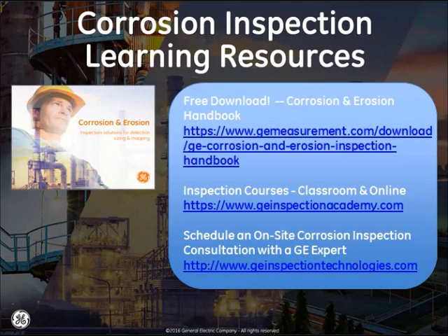If you do have a very wide area, for example, an area that could be 2 feet by 2 feet, and somewhere within that area you think you have a concern of corrosion wall loss, that's when the array imaging systems really shine, because you can scan a large area like that very, very quickly. And then once you determine where the suspect area is, then you can go in with the point type single element thickness measurement. In terms of tank bottoms, for example, typically you want to inspect the entire tank bottom area. These tanks can be 60, 80, 90 feet in diameter.